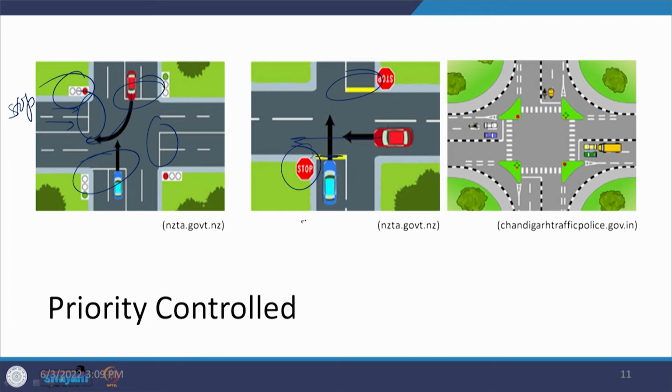So, it is a two-way controlled system rather than an all-way controlled system, and the reason is that this can be a minor road where this one is a major road. The traffic on the major road is allowed to move at its speed, whereas the traffic coming from the minor road has to get the opportunity to cross or to merge into it.